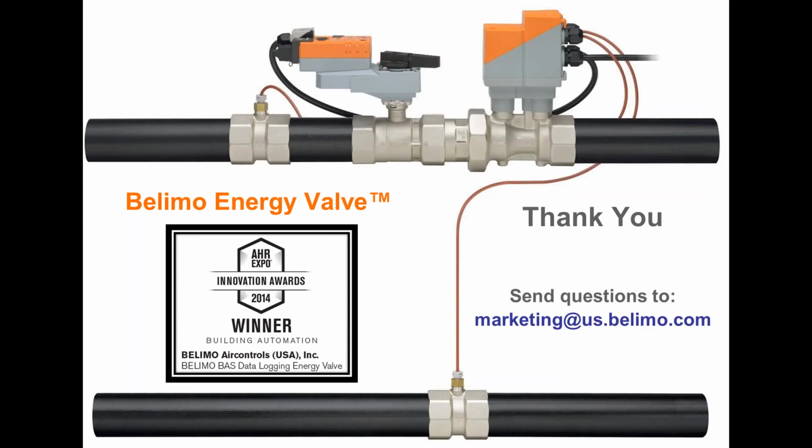That's the simplified explanation. So Belimo Energy Valve communicates in a bunch of different ways. It has an analog output feedback like a standard actuator. It's also a BACnet capable device, and through any of those types of communication you can receive valve position, and that will allow for the employment of that strategy. Now, all of you who are not in California are saying, yawn, I don't care, but keep in mind there's very similar language in ASHRAE 90.1, and so if you live in a jurisdiction that's adopted ASHRAE 90.1, make sure that you're keeping an eye on that as well, because that's definitely a factor for the whole country.